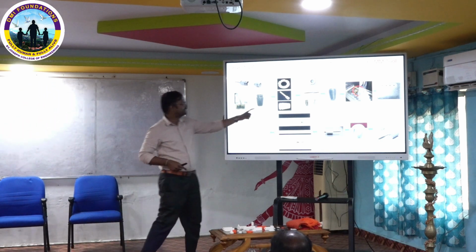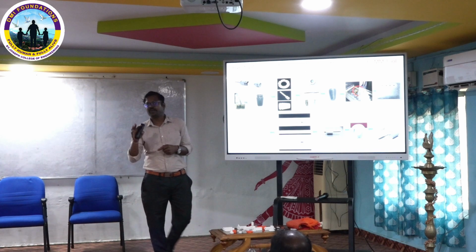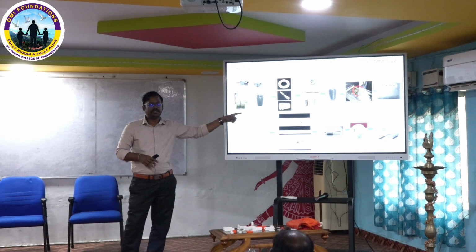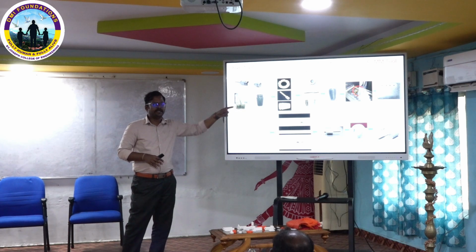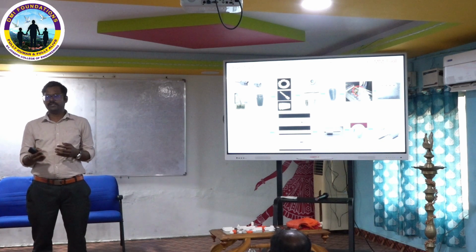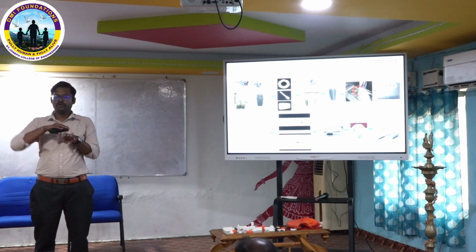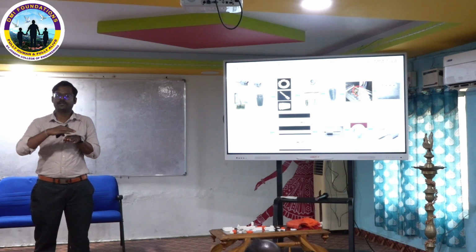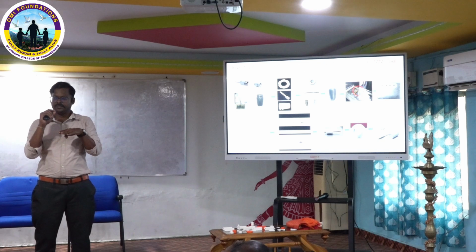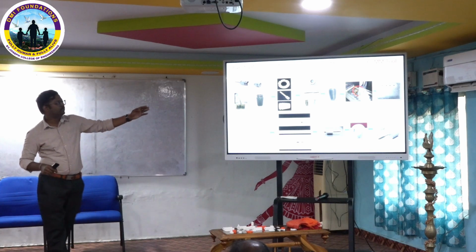When I changed the design and fixed it, I could easily hold the tool and achieve movement also. But I faced a conductivity problem. So I did electroplating on the ABS material. Initially I couldn't do it. So first I did electroless plating, which removes the butadiene layer on the surface of the ABS component. Then I deposited nickel as a minimum-thickness initial layer. Then I did electroplating on that to increase the thickness of the nickel coating. Then I used that one